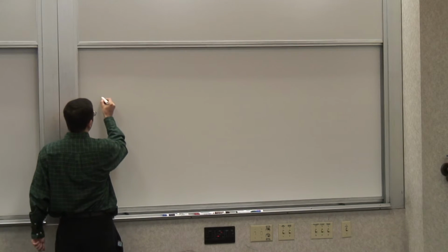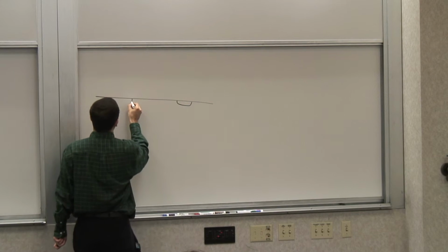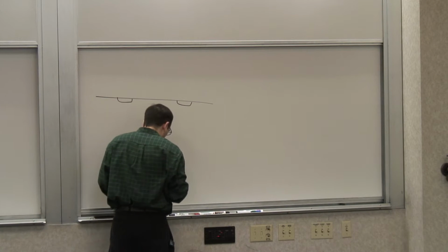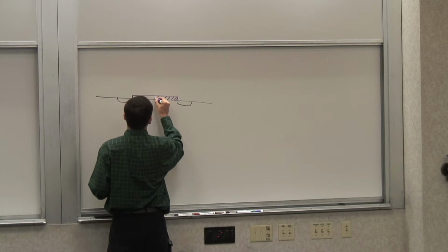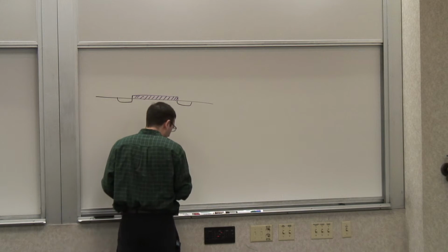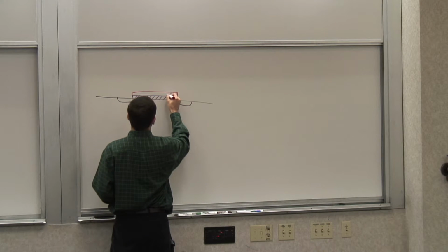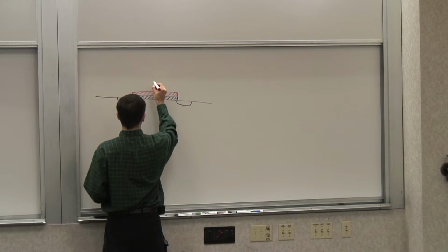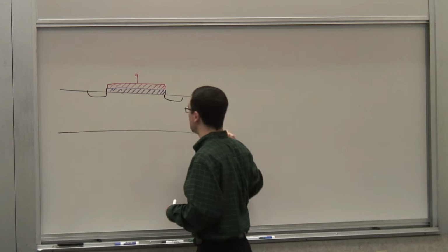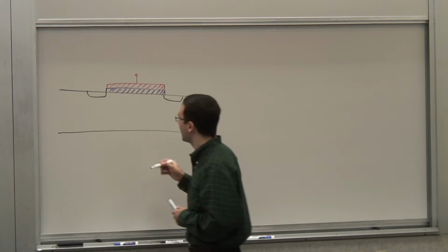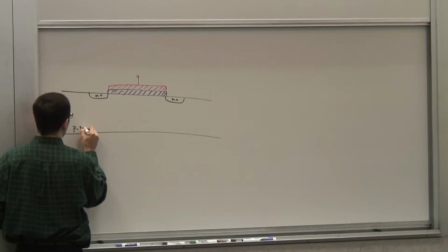So what we did, we created this MOSFET where you had the oxide, or the insulator in general, and then you had the gate material, which was some sort of conductor. We call it metal, although most of the time it's not made out of metal. And then we saw that we could have this device, and in general, it's built on some sort of substrate. So let's say it's an NMOS. So we have N+, and then we have P substrate.